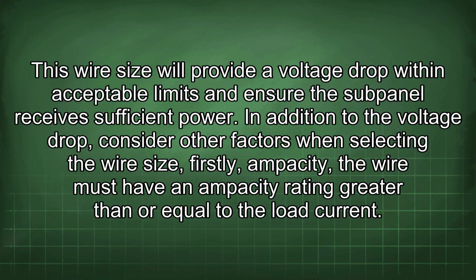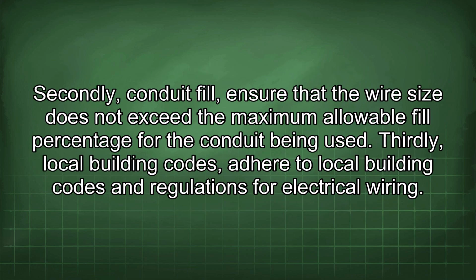In addition to the voltage drop, consider other factors when selecting the wire size. Firstly, ampacity. The wire must have an ampacity rating greater than or equal to the load current. Secondly, conduit fill. Ensure that the wire size does not exceed the maximum allowable fill percentage for the conduit being used. Thirdly, local building codes. Adhere to local building codes and regulations for electrical wiring.